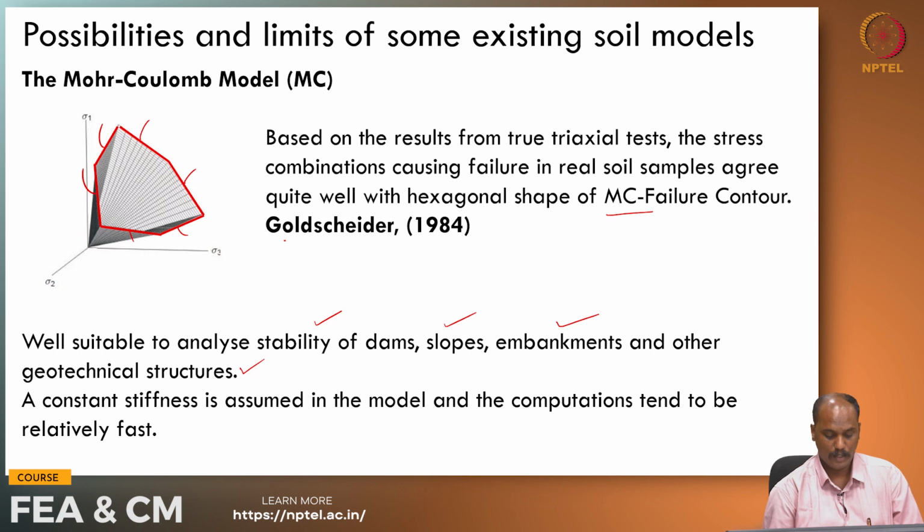We have to be cautious on one aspect, that a constant stiffness is assumed in the model, which we will discuss in the subsequent slides in the form of limitations. The other advantage is the computation: the time that is required to run your analysis is very, very fast. Why is it fast? Because the stiffness is assumed to be constant in the model.